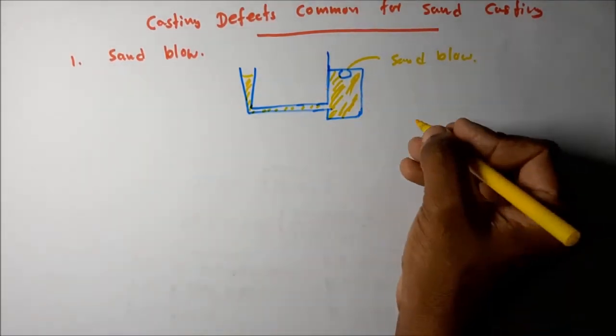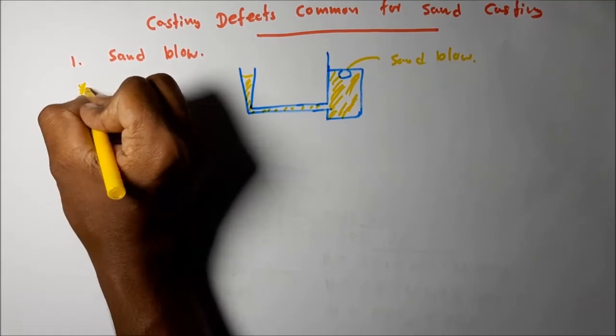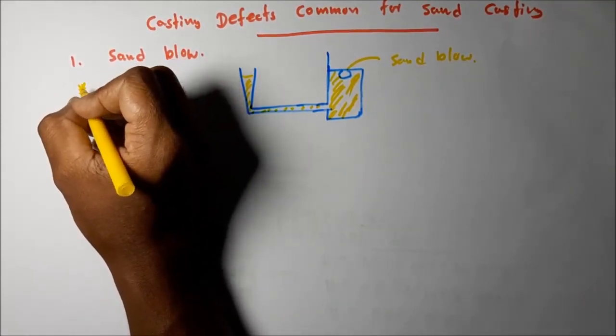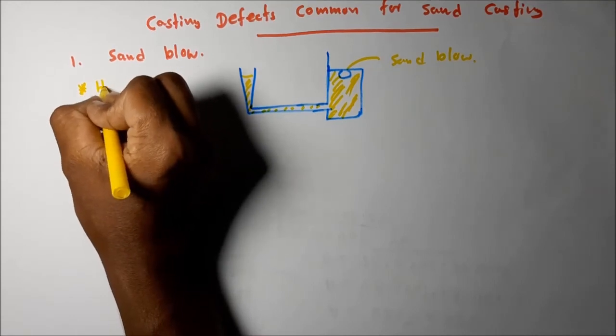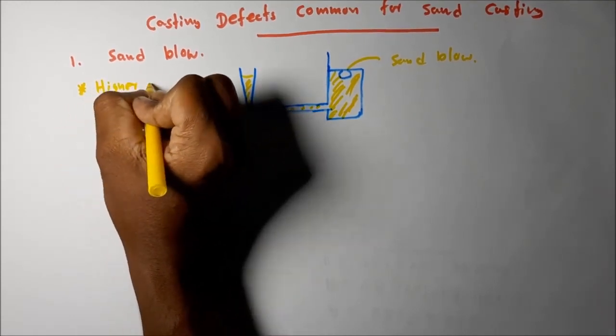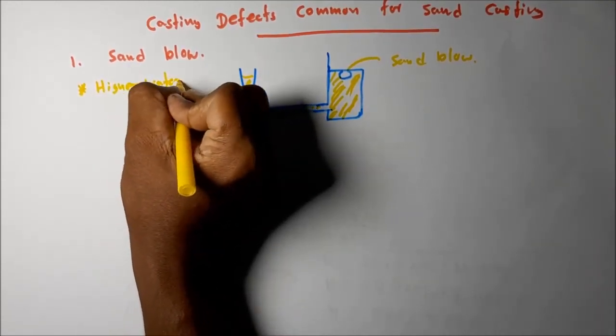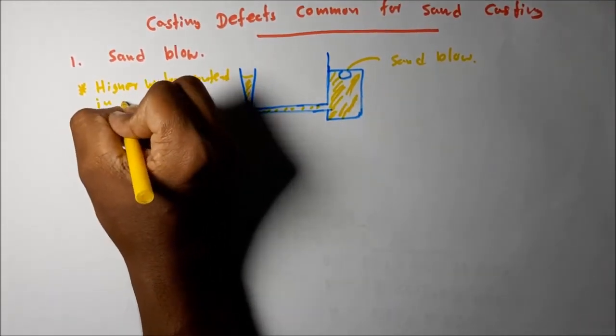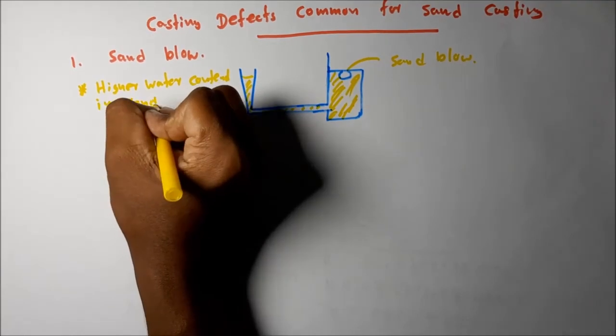What is the reason for this sand blow? The reason is higher water content in the sand mixture.